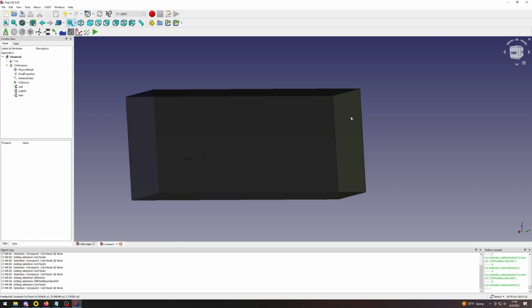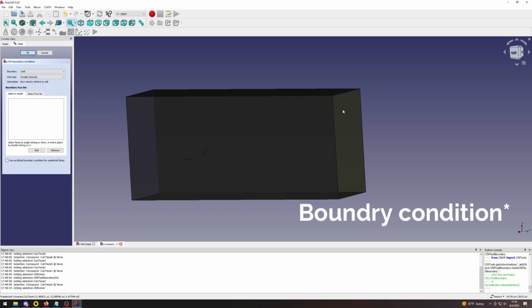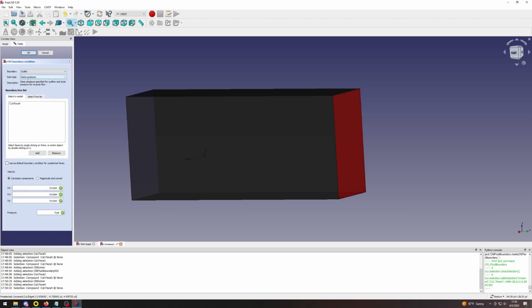of the wing. So we're going to click on that solver again, add a new boundary layer, select that, click add. That's what I forgot to do last time. So now that face there, we're going to make it an outlet of static pressure. And we don't have to do anything else to it.